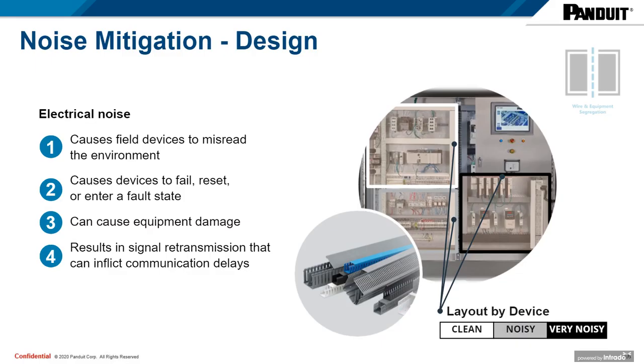As we all know, electrical noise in a control panel can lead to significant problems. Specifically, it can cause field devices to misread the environment, devices to fail, reset, or enter a fault state, signal retransmission that can inflict communication delays, and in some cases, even equipment damage.